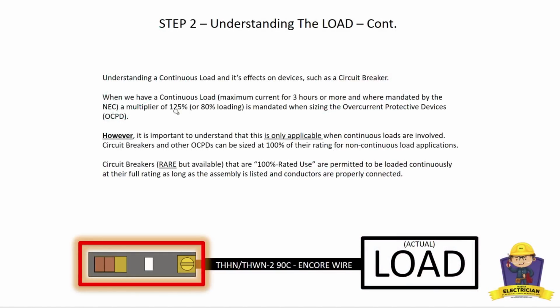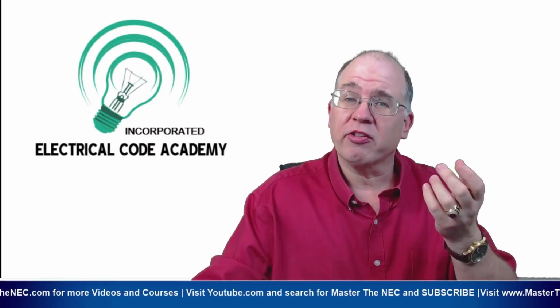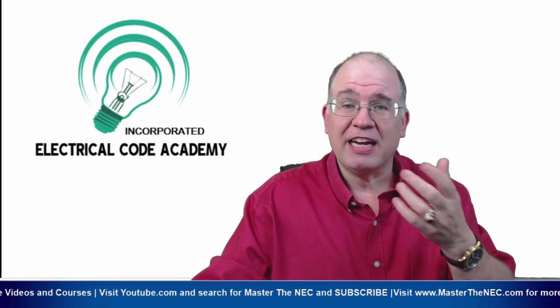Now, when we have a continuous load, the maximum current for 3 hours or more, or somewhere the code mandates it, then we have to take a multiplier of 125%. However, it is important to understand that this only applies when continuous loads are involved. A circuit breaker or other overcurrent device can be sized at 100% of its rating for a non-continuous load. So a circuit breaker that's rated 20 amperes can handle 20 amperes indefinitely if it's a non-continuous load.